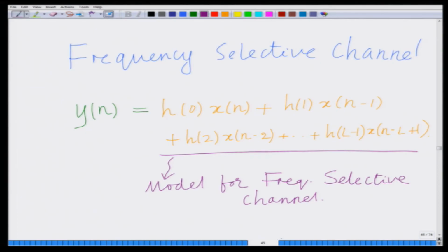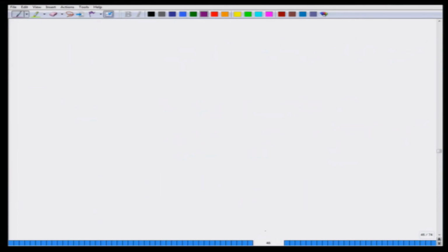As we said previously, in the OFDM system we generate the transmit signal using an IFFT operation. So, let us do the following. Let us consider the first set of symbols X0 tilde, X1 tilde, so on up to X n minus 1 tilde. These are the symbols that are loaded onto the subcarriers, and then I process them using the IFFT operation to generate the samples x tilde 0, x tilde 1, up to x tilde n minus 1.